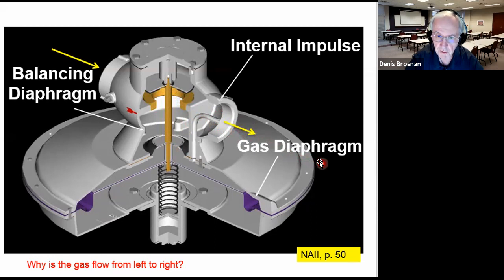The pressure regulator really regulates the flow, regulates the dynamic pressure through the system. And in this valve, it's relative to atmosphere. So there's a gas diaphragm in here. It's only shown in part here, but it comes all the way across, and it's going to oppose the movement of this particular spring right here, which is adjustable.